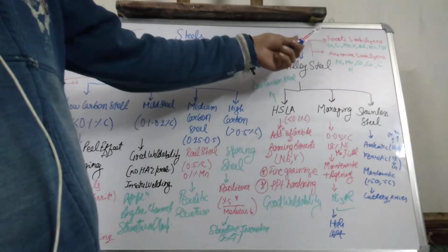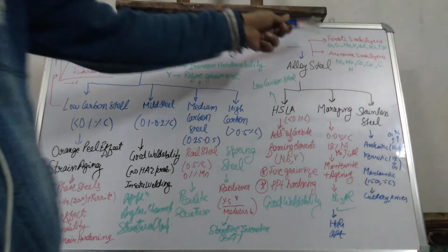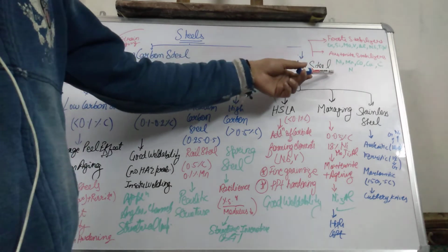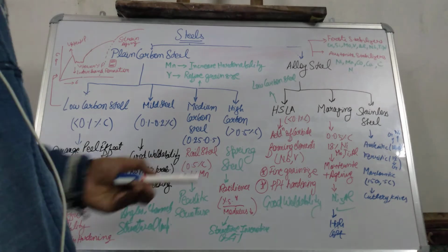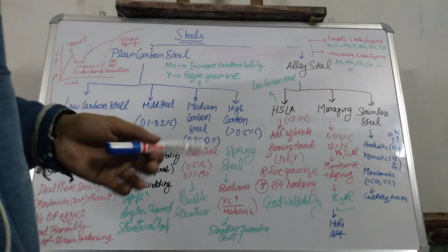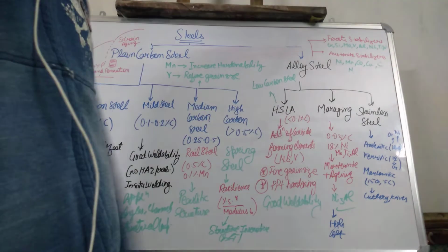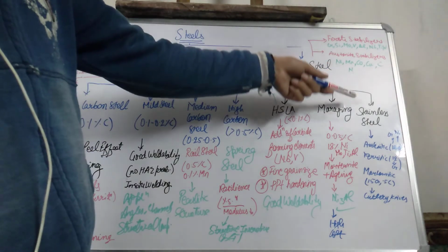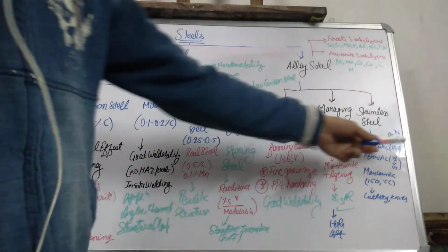Ferrite stabilizers have no austenite phase field, so they cannot be heat treated because no austenite phase transformation is possible. Based on this, we have stainless steels. Obviously they are stainless because they have a passive oxide layer of elements such as chromium oxide, which prevents them from degradation. They are classified into three categories based on their properties. One is austenitic stainless steel. As the name suggests, they have addition of alloying elements which are austenite stabilizers. The main one is nickel.